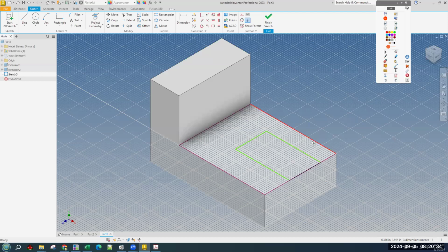First of all, if you don't have auto project edges for sketch creation and edit, that one setting I told you to change, the thing we just did probably didn't work. You probably weren't able to do the L shape that I made because it required snapping to things, but that's fine. All right, so we are, for this one, going to dimension essentially the location of the sides of the rectangle rather than their lengths.